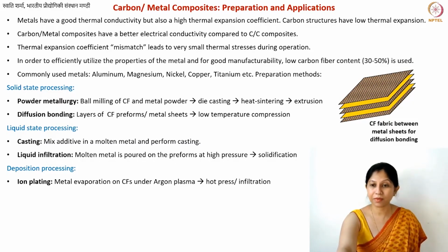Third one, as the name suggests, we are depositing something. What are we depositing? If you remember from the carbon composite class, we talked about pyrolytic carbon deposition on top of the carbon fibers, pyrolytic carbon from gaseous hydrocarbons. Something very similar, but here you don't have the carbon being deposited, but the metal being deposited on top of your carbon fibers. This can be done using evaporation techniques.